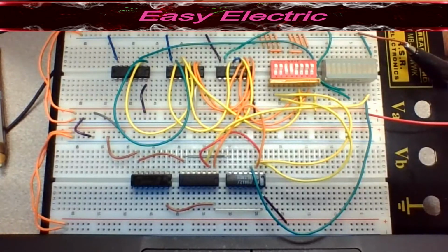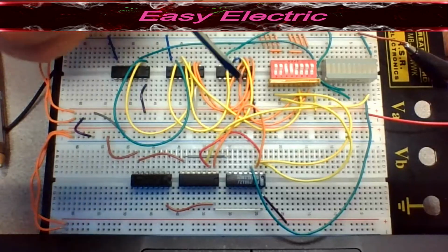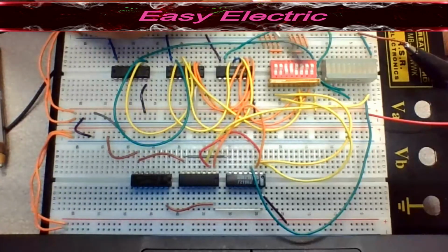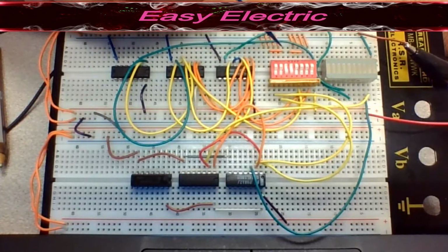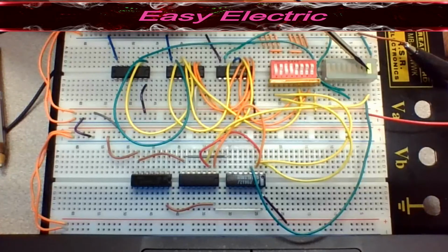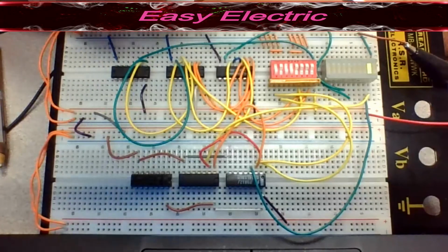So let's check all 4 different cases, or 4 different bit patterns, that we could give to the input of the half adder. As I mentioned, this is A, this is B. Right now both are 0, so the output is 0, 0. 0 plus 0 is 0, and that one is right. The next could be 0, 1. So A is 0 and B is 1. I change B to 1. 0 plus 1 should be 1. As you could see, the lowest value bit is on and the highest value is 0, which means you have a binary 1, which works.